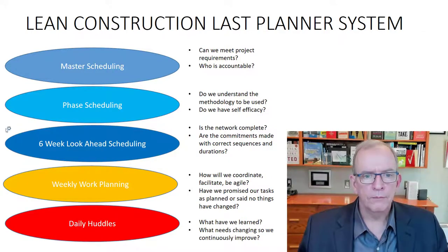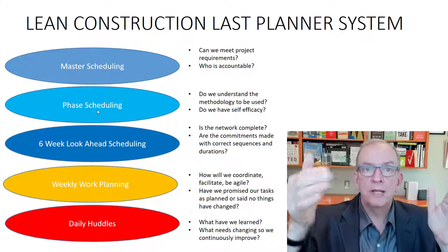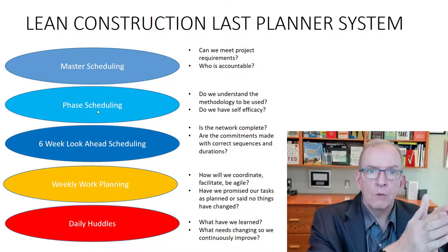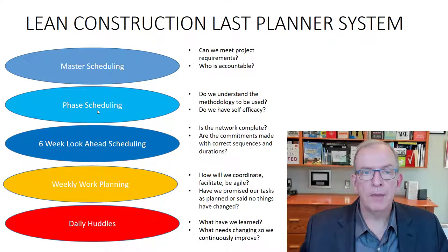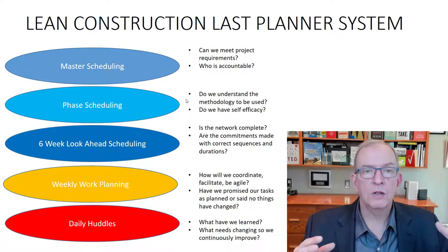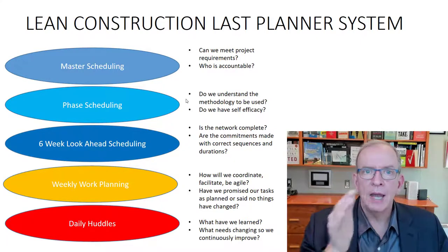And at that point, we're actually going to gather together the trades that are involved in the project. And we are going to do what we call a pull planning session, where we actually schedule that milestone back to the start. So if it's 4 months out, we're going from 4 months back to today, or back to when we plan to start that work. And we're utilizing them, and we're really getting them involved deeply in that planning process. They actually call it a big room, where you collaborate in a large room and you spend some time going through that, detailing out the schedules.